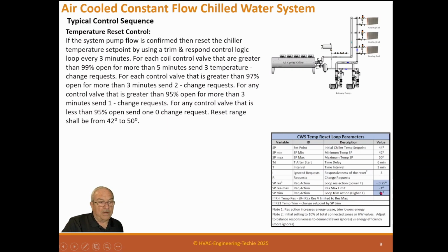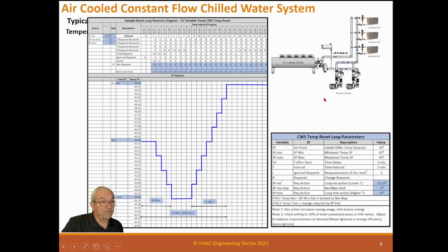I think these work, and I have a way of testing this, and I'll show you that in a second. So now remember, this is a constant volume, so we're not going to reset flow because it's constant. So we can reset temperature, which will save us some energy and will make the system operate better. And here's my little handy-dandy chart.